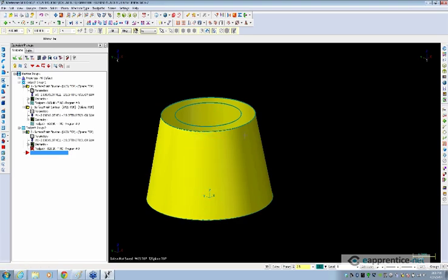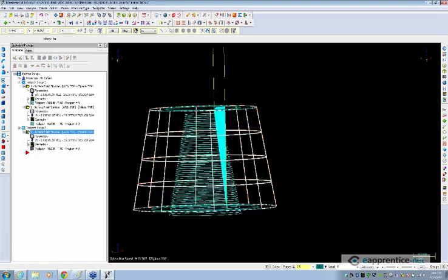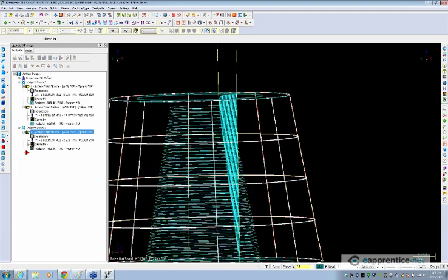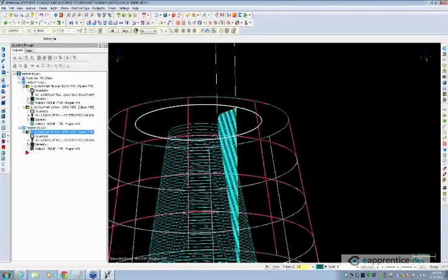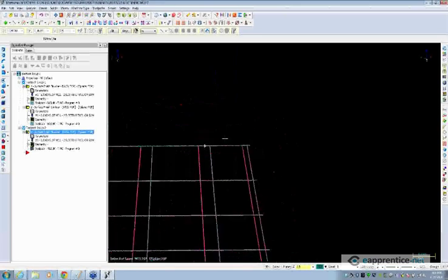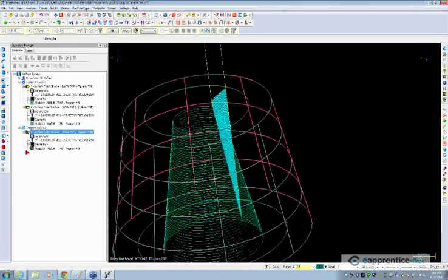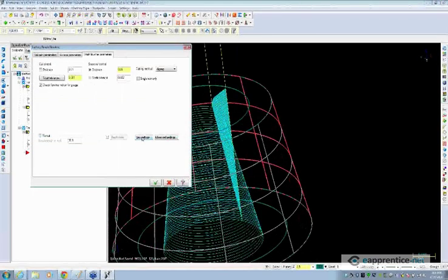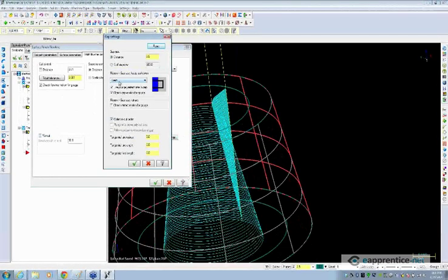When we get to the edge of each slice, so here you can see that we've got some slices that are being cut. Once we get to the edge of the slice there, we're going to need to control that toolpath motion. So under gap settings, there are some check boxes here. Check gap motion for gouge, use plunge, retract rate in gap. This just controls the feed rate that gets used, but this check gap motion for gouge is what is causing this retract to happen.